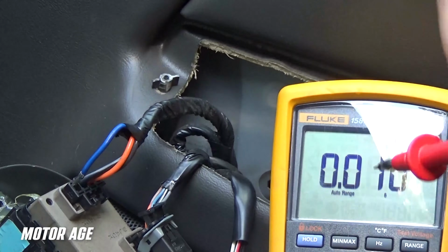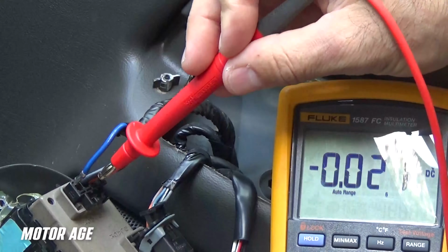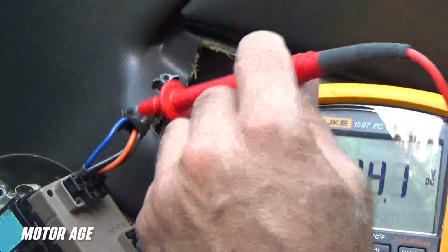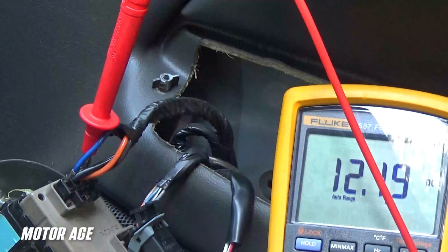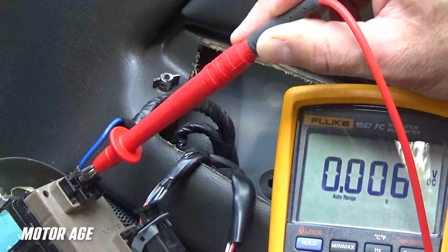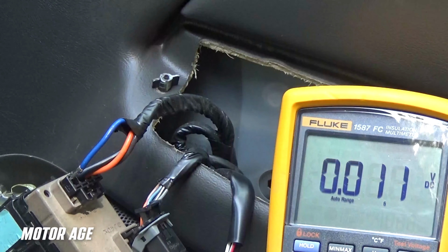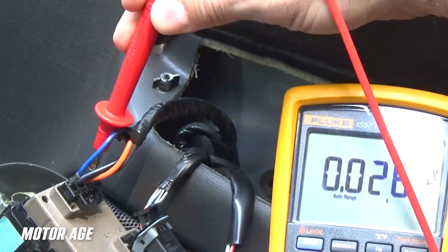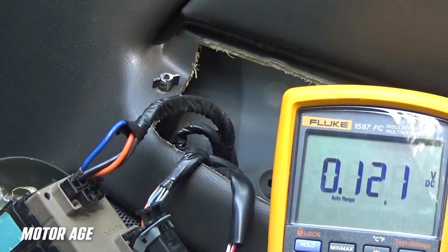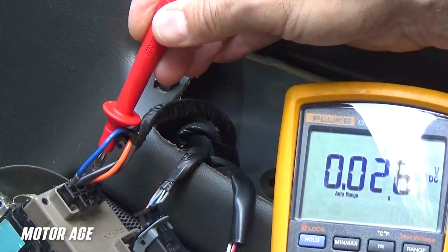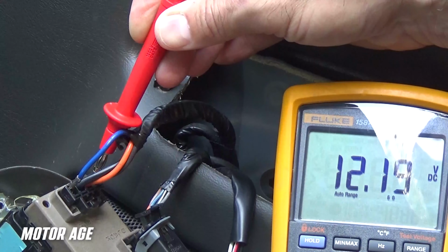So I'm going to operate the switch now, and hopefully that 12 volt source that we just tested is going to make its way through the switch and out to the power window assembly, through the assembly, and back to the switch again on the ground side. So our orange wire is our source coming in from a fused source, and we've got 12 volts available. Now we're going to move over to our brown wire, and the brown wire should have 12 volts on it when the switch is placed in the down position. So I'm touching the wire, switch is in the down position, and we have 12 volts leaving the switch.